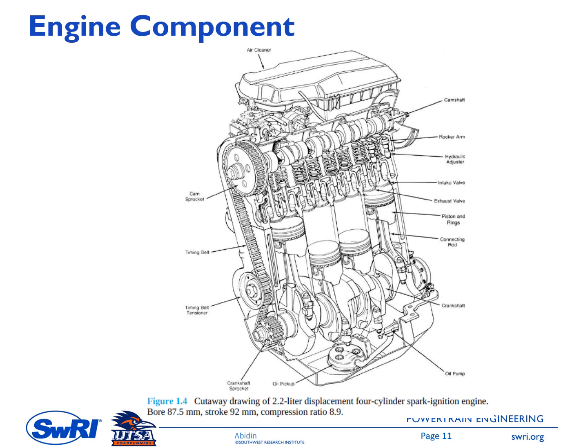The next one is looking at the engine components. I'm sorry the picture is not great here, but hopefully you can see the main components of this reciprocating engine. You can see here we have 4 pistons. Okay, piston number 1 and then number 2, 3 and 4. So we have 4 pistons and it is inline. Why is it called inline? Because the axes of these chambers are in one plane. So later on I will show you a different engine geometry.